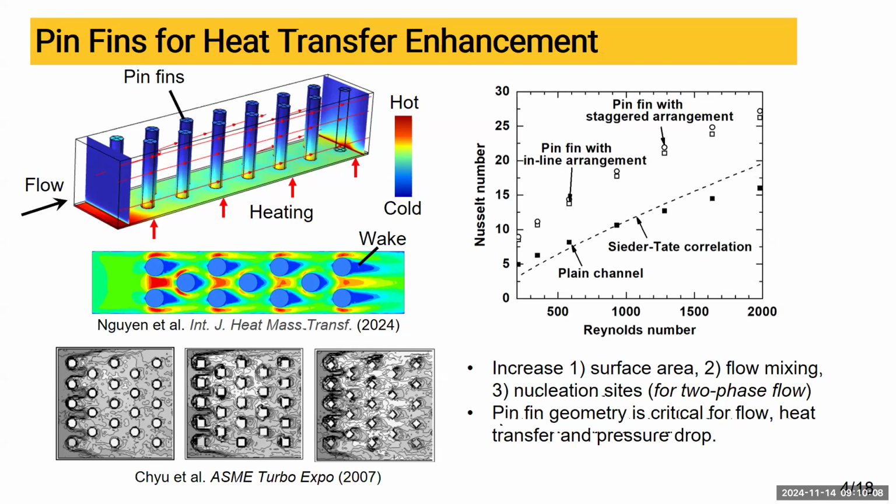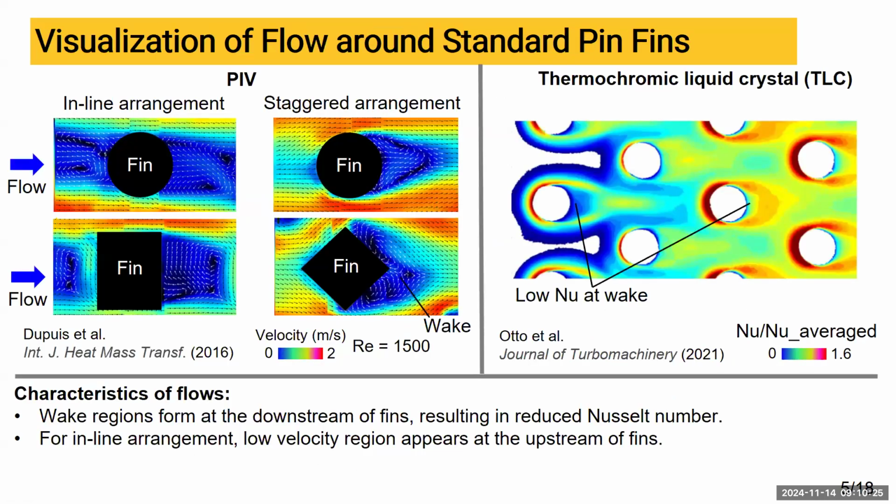Because of its popularity, a great number of works have been done, both numerically and experimentally, in the past to study the heat transfer performance of these fin shapes. In order to experimentally understand the flow patterns and heat transport around these pin fins, researchers have used PIV and a technique called thermochromic liquid crystal, TLC. I tried to find an example with LIF for pin fins, but it seems no work has been done with LIF and pin fins before.